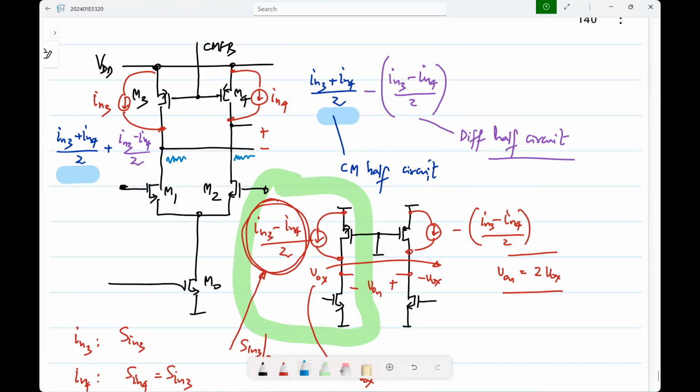No, I mean that's the definition of differential, right? Common mode means whatever is the same on the two sides, differential means whatever is opposite on the two sides. Right, that will contribute to common mode noise. No, it cannot, because it's the same for the two sides. It is like the noise from the tail source.